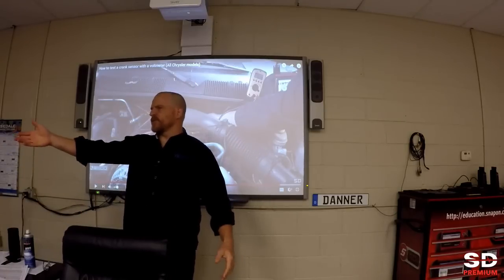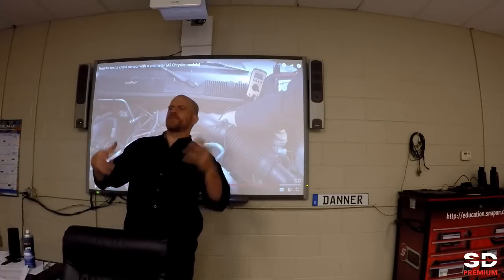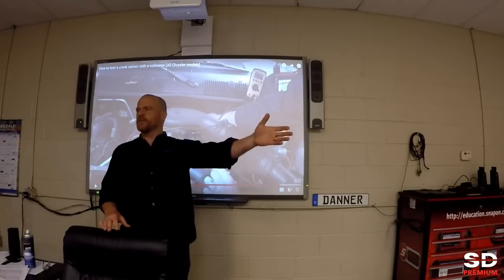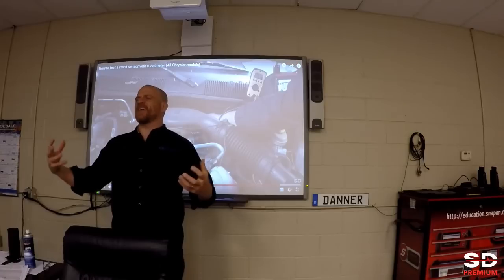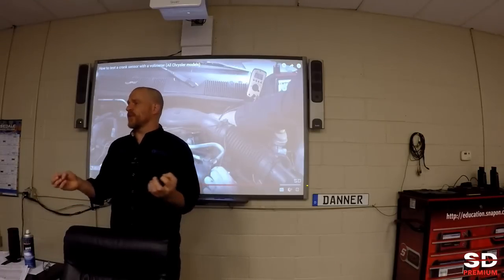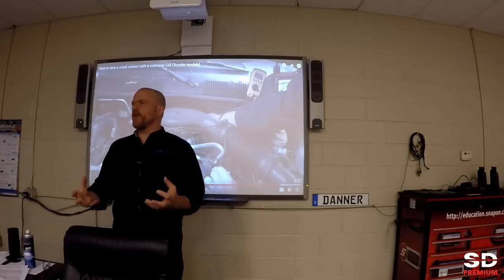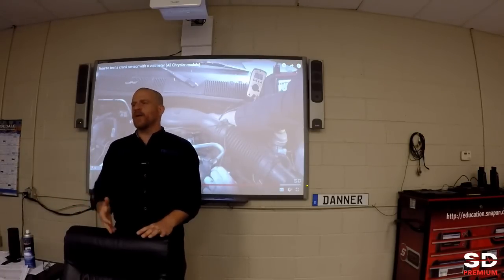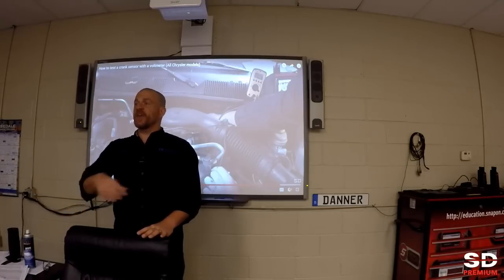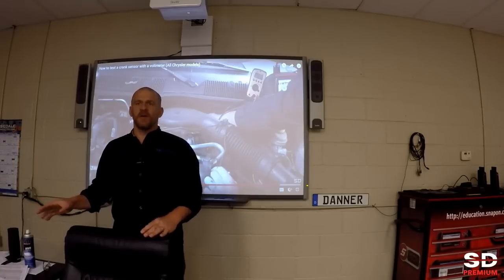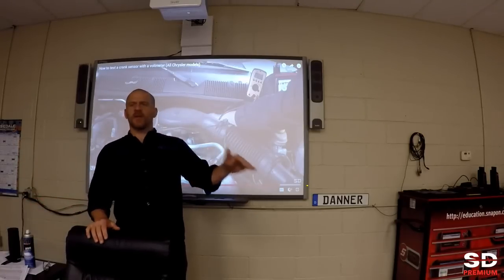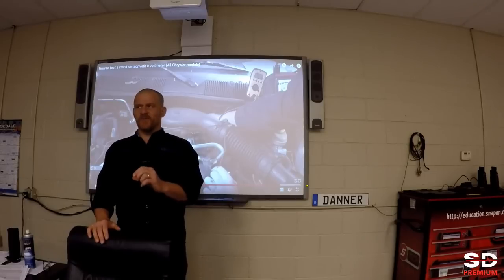It was relays clicking too, because when the computer receives an RPM signal, it turns the fuel pump relay on. So the other, and I think the auto shutdown on a Chrysler. So the clicking you're hearing is actually relays turning on. Does that in itself tell me that my wiring is good from the sensor to the computer? And let's say that we didn't have an RPM signal before, we didn't have spark, and you're pretty sure it needed a crank sensor, and you wanted to be 100% certain.